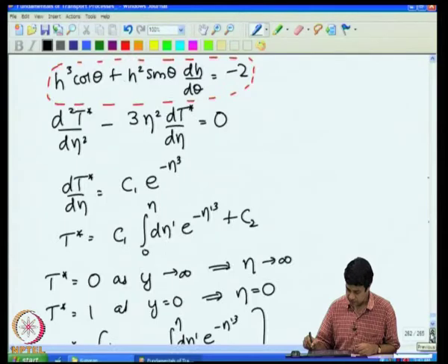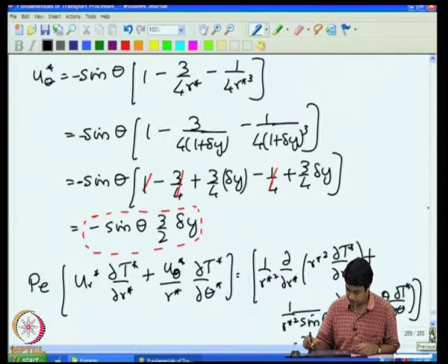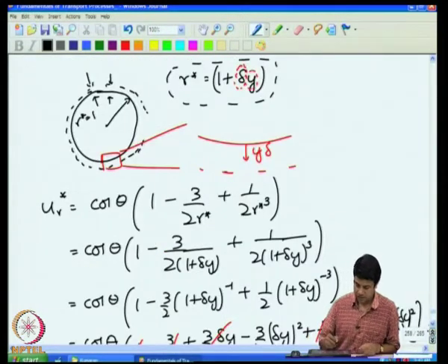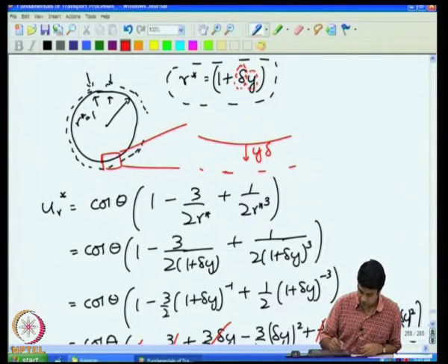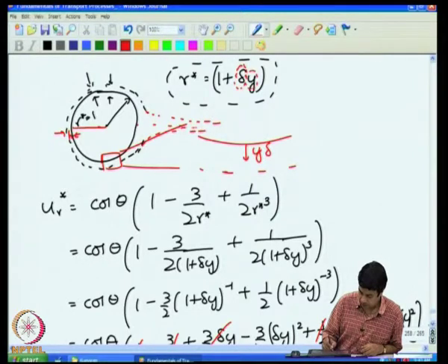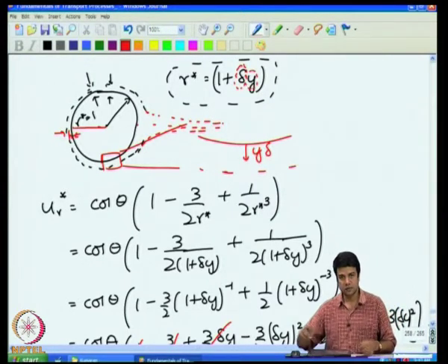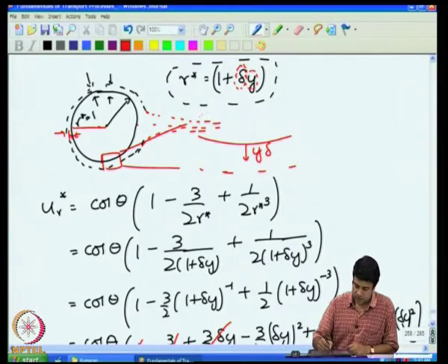What that means physically is that there is a boundary layer around the sphere, but the part that I did not continue for you here. This is the upstream side. Here you have some finite value of h on the upstream side. However, downstream side h actually goes to infinity. That means that the boundary layer looks something like this. The value of h actually goes to infinity as you go downstream. This region here is what is called the wake.